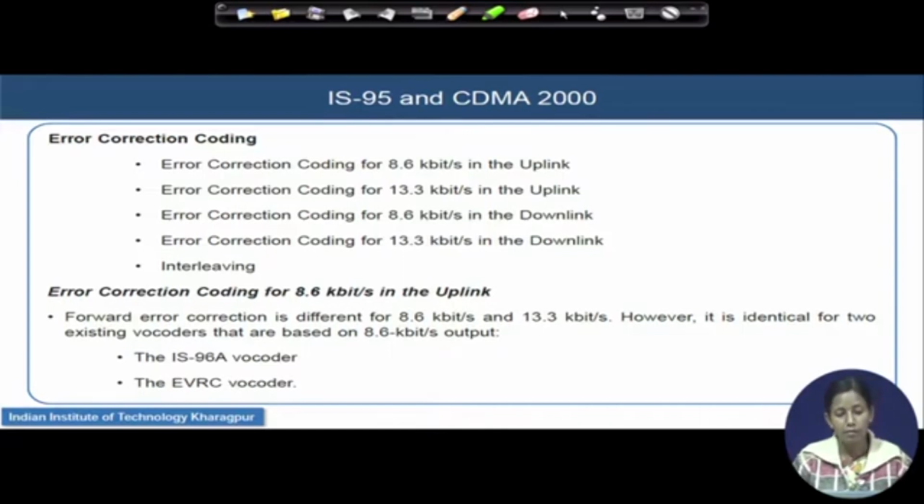And remember, after coding we provide interleaving, and the coded bits are not released in the air directly. To get the maximum coding gain, the interleavers should be accompanied with the error correcting codes.